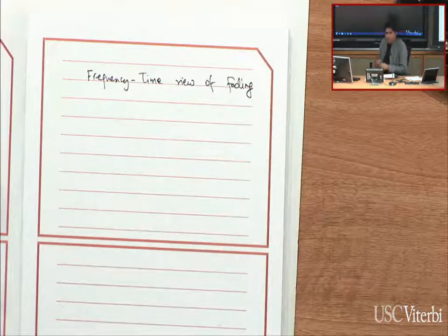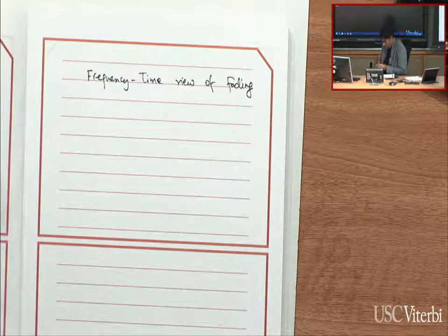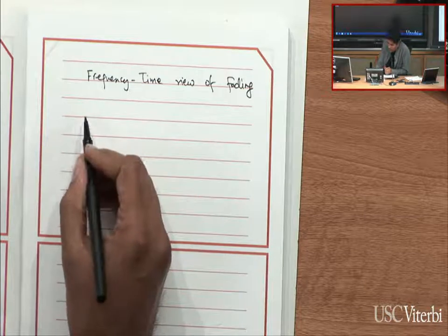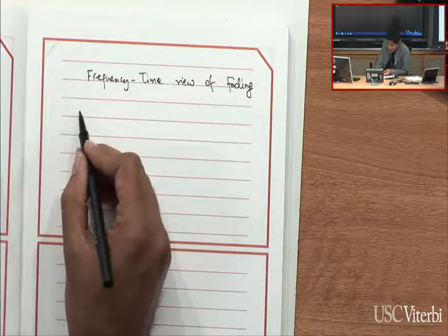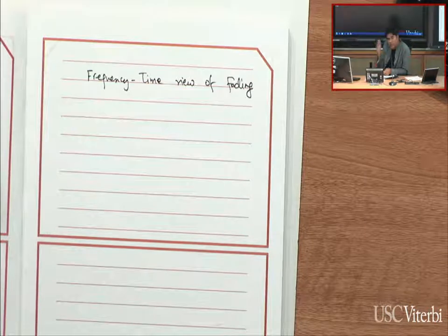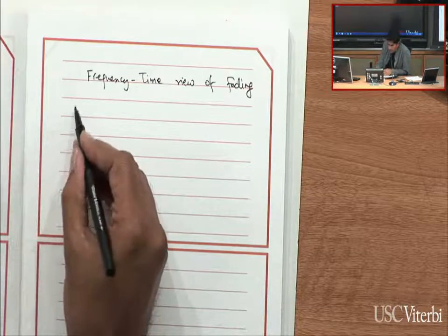So it turns out that there's a little bit more subtlety to how fading happens and what the challenges and opportunities are that it presents. One issue with fading is an issue of these multipath reflections causing delay in the signal as it arrives. Okay, so this is called the delay spread problem.